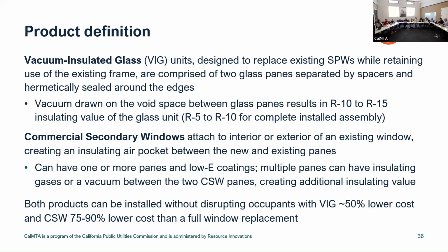Secondary windows are slightly different. With secondary windows, I would not do anything to the glass. I would just go up to that opening right there, and it's not unlike your storm windows if you have them in an old house, or I always had the job of installing them for grandma at Thanksgiving. These are just going to slide into place, so you're not removing anything.